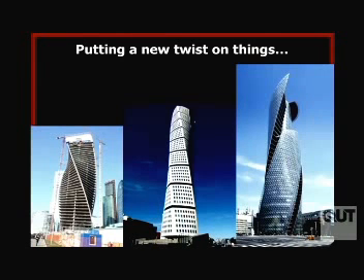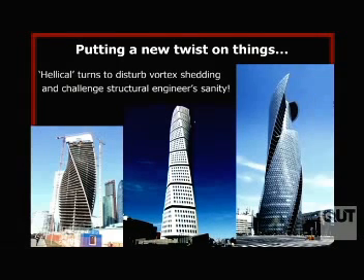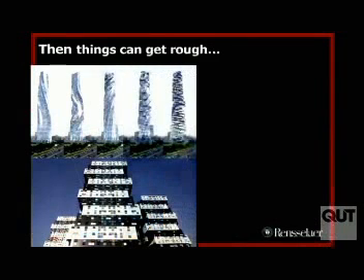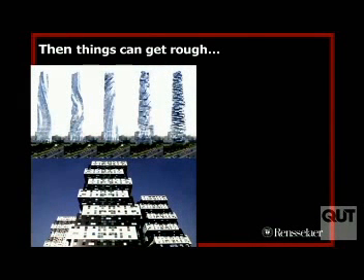The building on the left is in Qatar, I think, it's now completed. The building in the middle is in Malmö, Sweden. These turning torsos or twisting buildings are again great ways of disturbing the flow. They act, if you like, as giant helical strakes on chimneys, to disturb the flow and improve the performance. And then there are other ways of disrupting the flow.